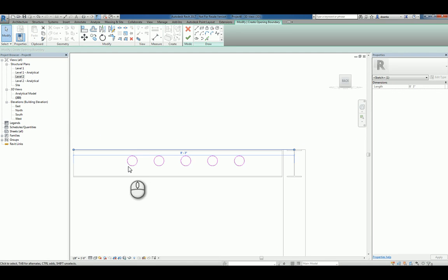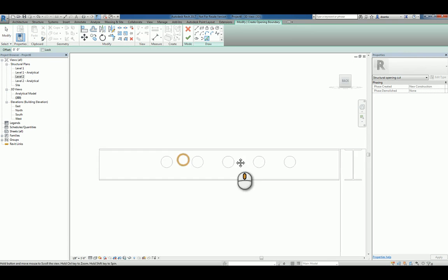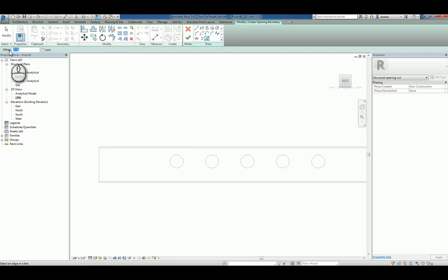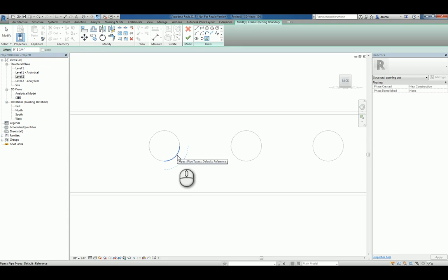Let's delete the line work that we've created earlier, and use the Pick method again, but this time set an offset. Let's assume you have a 1-inch insulation around the pipe, plus say 1/8 of an inch. So let's do 1 1/4 as an offset. We'll zoom in here and pick this. Again, this time I won't lock it, just for the sake of speed.